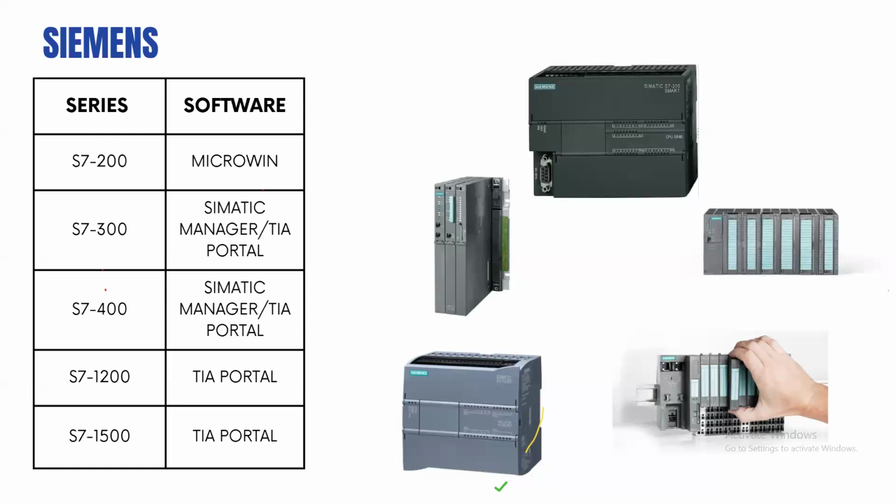But what I would say is that Rockwell is also changing. Because of competition in the market, they have seen that they have to open up some of their PLCs. So before, and this is not part of the scope, so nobody should ask me further questions on what I'm about to say, if you wanted to do Modbus on a Rockwell controller, what you would have needed to do before was to buy a ProSoft communication module. But now, for I think up to 5 devices or so, you have a Modbus block that is now available on the modern ControlLogix and CompactLogix PLCs.